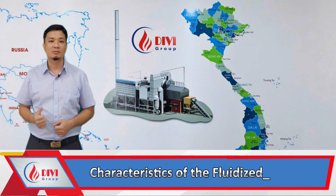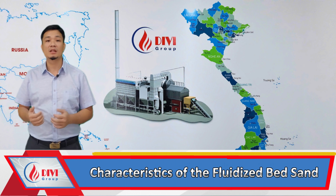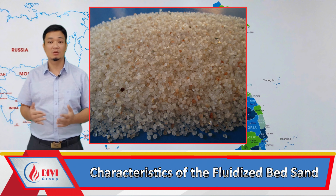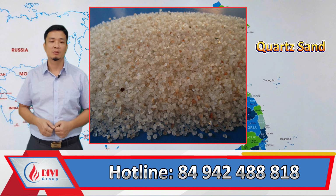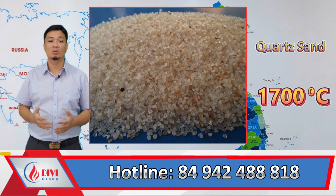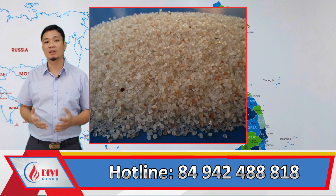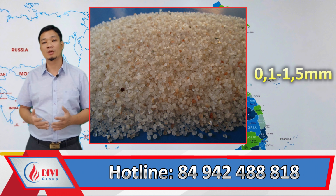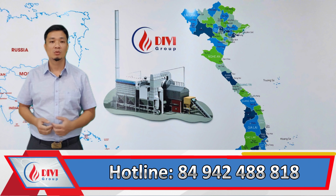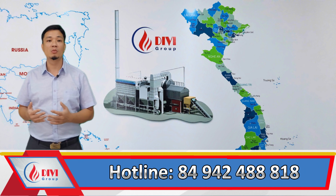Now let's move to the next point. Is there anything special about this sand? Can it be replaced with something else? Typically, when the fluidized bed material is sand, it is quartz sand, which has high thermal resistance up to 1700 degrees and is inert, meaning it won't fracture or break. These sand grains are uniformly sized between approximately 0.1 mm and 1.5 mm, depending on the type of fluidized bed boiler. The grain size can be adjusted based on the manufacturer's design if there are special requirements.